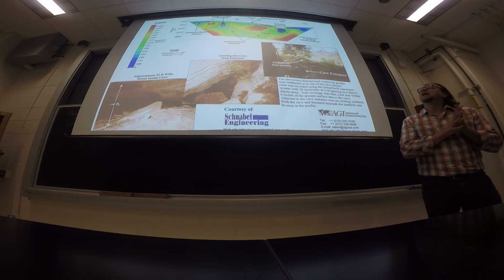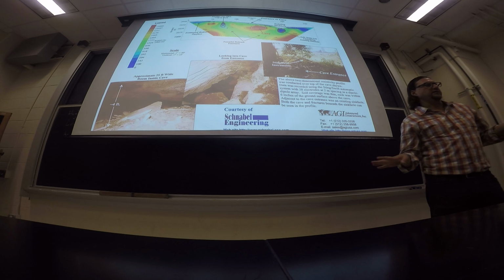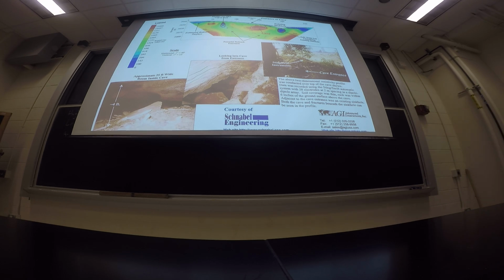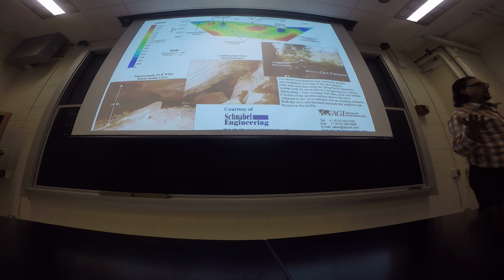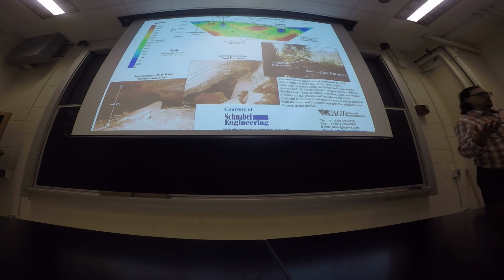Caves. There are places in the world where you've got constant near-surface conditions and people don't know about it. They want to build something on top of that property, but there might be sinkholes present. We've all heard of examples where something is built on a property, and then years later suddenly a sinkhole forms, causing major structural damage. So one of the things you can use resistivity for is to look for areas where you have karstic terrain.